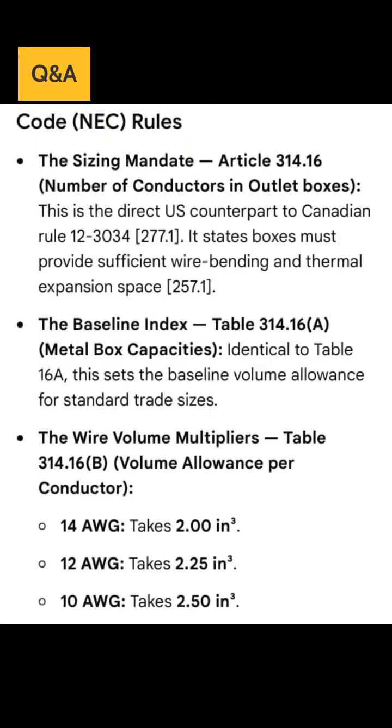The baseline index, Table 314.16(A), metal box capacity, identical to Table 16A. This sets the baseline volume allowance for standard trade size.